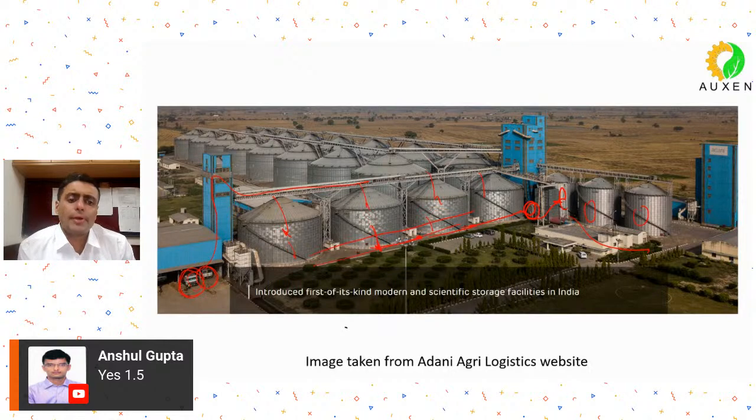In typical calculations, they take a 10% damping for the grain stored inside, 2% damping for the steel and 5% for RCC. So although the grain has a very high volume and weight, because it has very high damping, the overall multiplying values of grain come down.